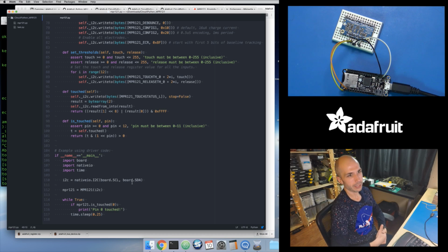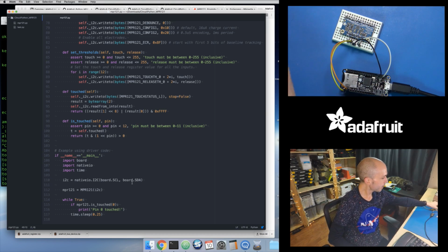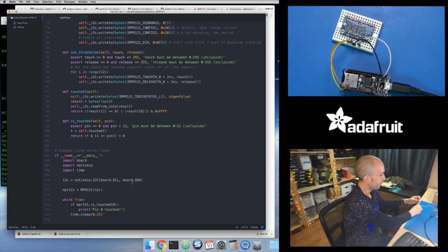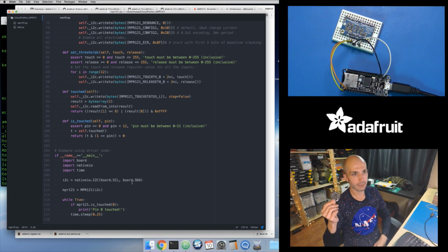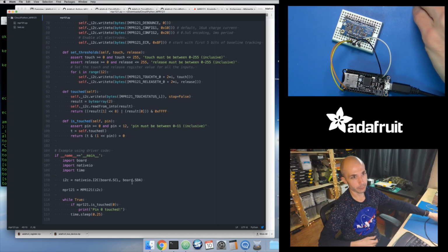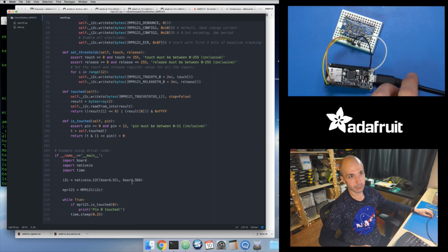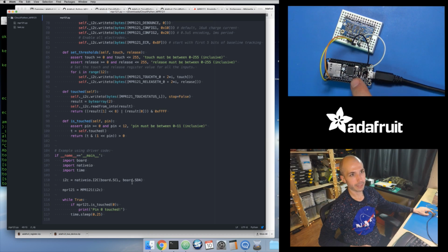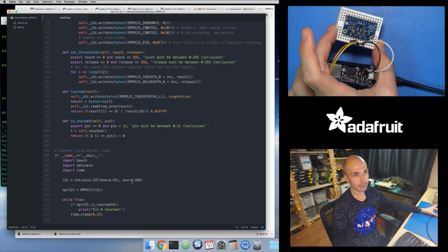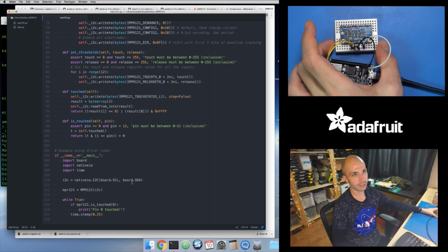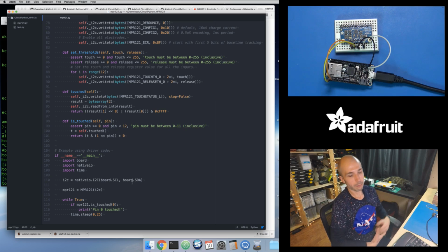But I just wanted to show in this video, like I said, that for the Circuit Playground Express boards, the boards that have the SAMD21 and the extra flash memory, they have native capacitive touch sensing built in, and we'll have that available. It's really easy to use with a simple little function call. And for the boards that don't have that, like the M0 boards you can buy today that don't have that extra flash memory, or this would work on the ESP8266 also, you can use a chip like the MPR121 capacitive touch sensing module, and you can see it's pretty straightforward.